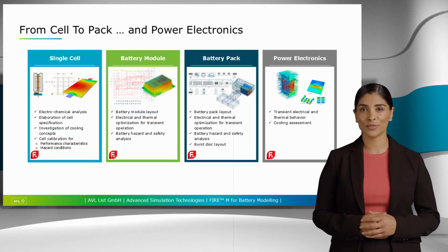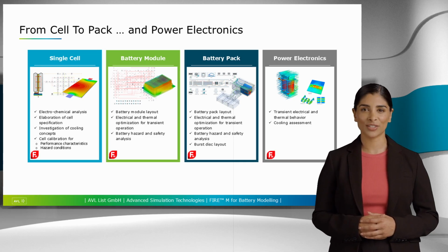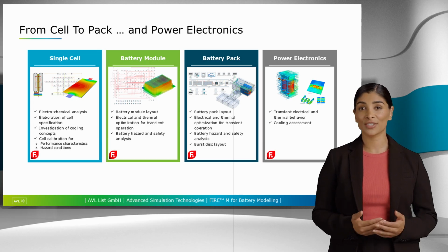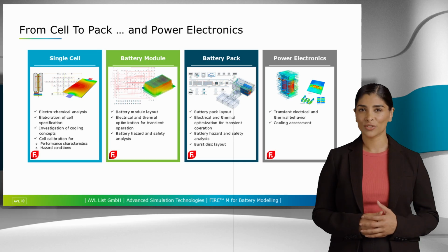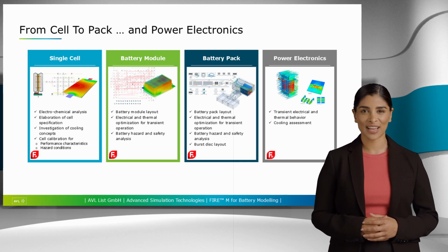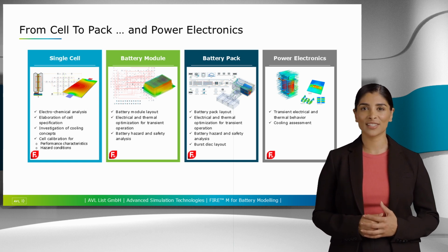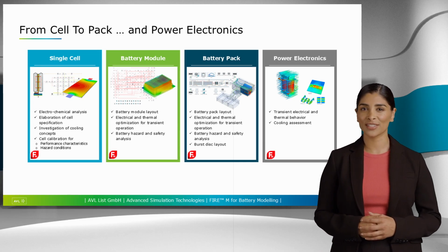FIRE M is applicable on cell, module, and pack level. Also, simulating power electronics is within its focus. On cell level, electrochemical, or detailed spatial temperature resolution is most often in the foreground of the investigations. For battery modules and packs, the focus is more on their arrangement and thermal optimization for transient battery operation, as well as on avoiding hazards such as thermal runaway.